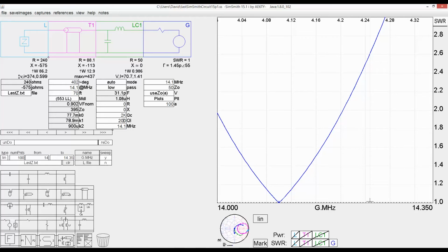The coil has a Q of 200, which is a reasonable value. If it had a higher Q, the losses would be lower. We've got about a watt of loss. So you start with 100, and we lose about a watt in this L network tuner.